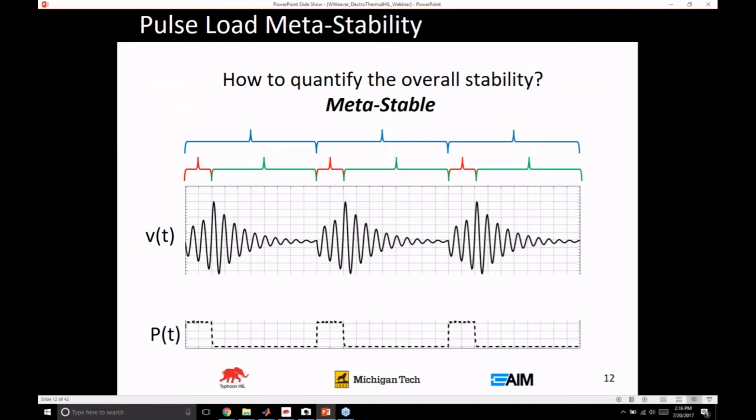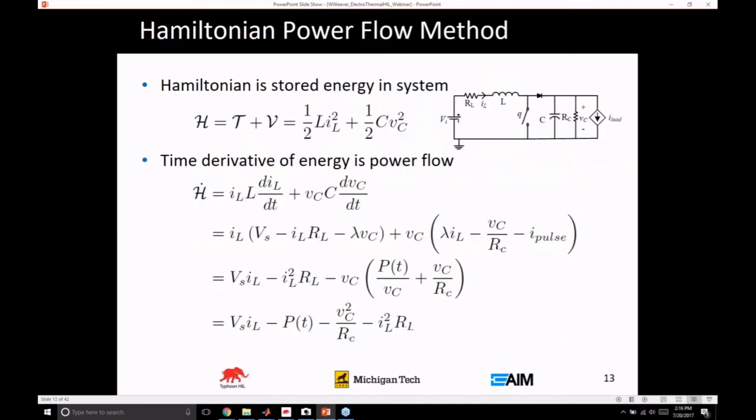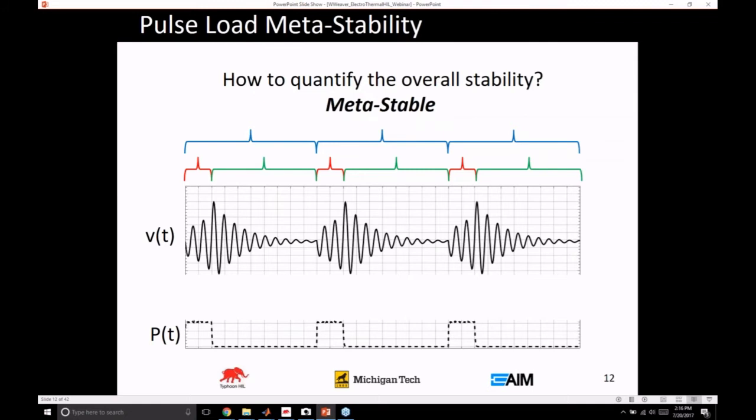It's not really a well-behaved system, but with proper design approaches, you can actually guarantee some level of operation as long as you're willing to let the voltage on the bus vary a little bit, and of course the levels are completely within the scope of the design on how much that voltage variation is allowed to wander. So how do you analyze this sort of system? That's the question. Linear methods, even periodic methods like Floquet, all sort of break down for this sort of analysis.